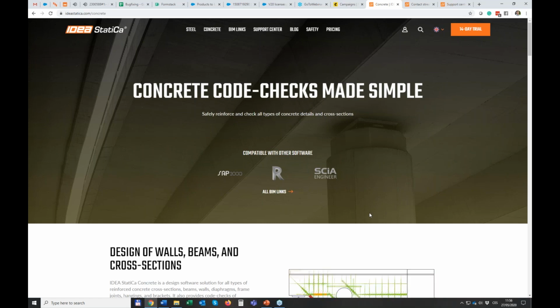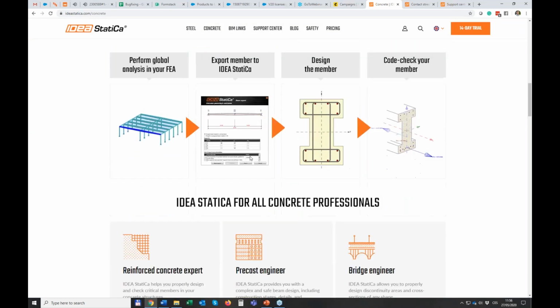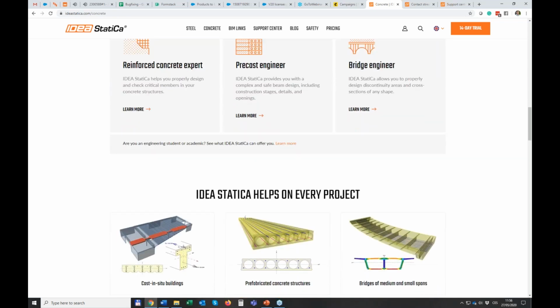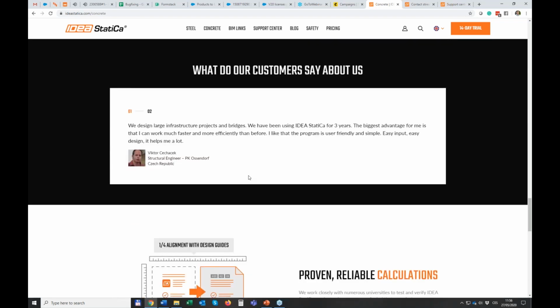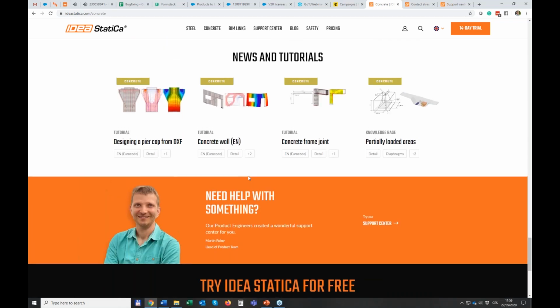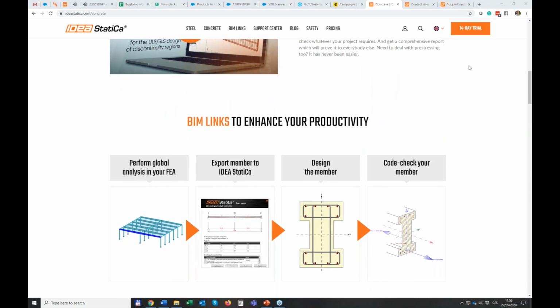Last question, concrete, that's on you, Orsi. The example is simply supported. However, in an actual situation, the end boundary conditions are complex. Do you allow the user to introduce the stiffnesses around the element under design? Of course, the supports are always a big topic, how you should support a concrete member. It depends on the real supports in the structure. You should always consider what the reality will be like, and it always requires some engineering judgment to apply the correct support in your example. So it's hard to tell when you don't have the materials for the real project, I think.